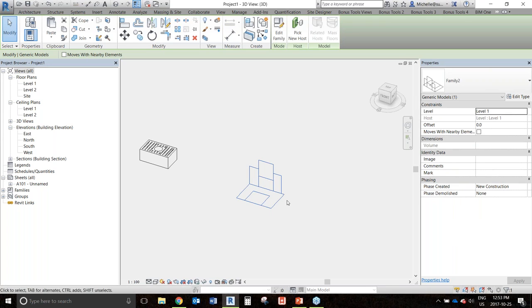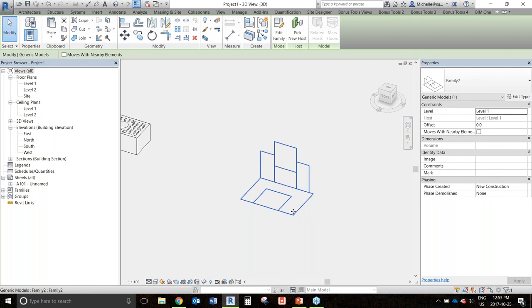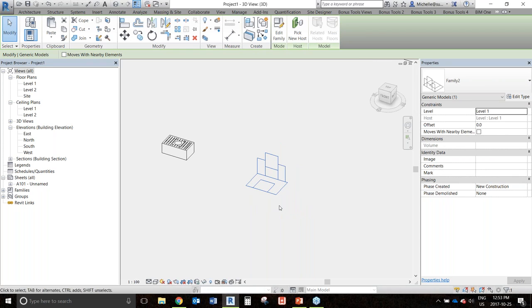So what you could do as a compromise, I've seen people in the past draw in plan, have those be model lines so that, if they do a 3D shot of their interior, they can see the furniture layout in 3D without having the actual geometry there. But you don't need to see your elevation in 3D or your side view in 3D. So those would be symbolic because they only show up as 2D in the view that they are in. So symbolic is basically the equivalent to detail lines in the project, and model lines are 3D.